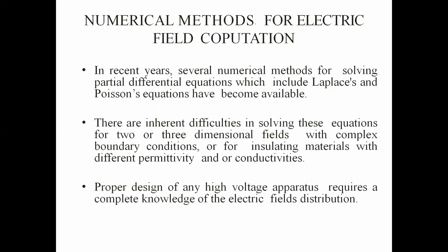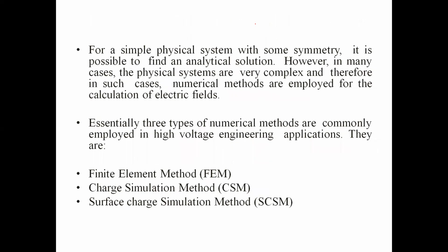In recent methods, several engineers have come up with ways of solving Laplace's equation or Poisson's equation. Some of the best methods we have are the finite element method, the charge simulation method, and the surface charge simulation method, which we'll use for calculation of this electric field stress.